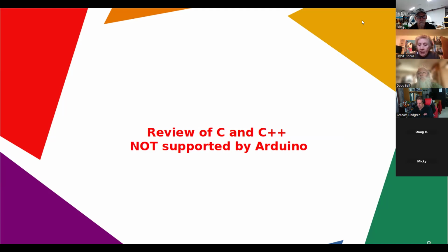Okay, so the next concept is exceptions. I'd already mentioned this before, but this is part of the dialogue I wanted to outline. Exception handling, specifically what's called try and catch blocks in C++, is not supported. Floating point operations, okay? While some Arduino boards support native floating point operations, they are often limited and can be resource intensive. Next point, string functions. Some standard string functions may not be fully implemented or optimized for the Arduino environment.